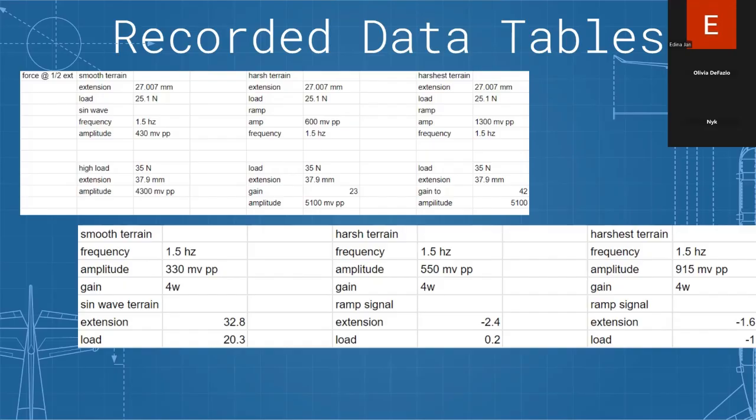The situations were chosen based on no loading, 20 newtons, which was this year's DBF plane weight, and 35 newtons as a maximum loading to avoid damaging the strut or the shaker table. Each situation was run for each of the three terrains.